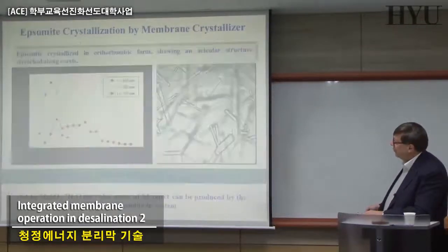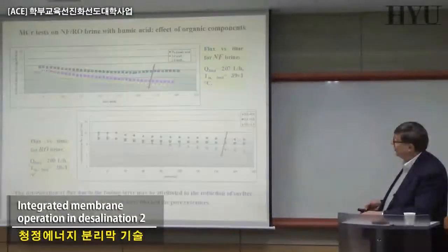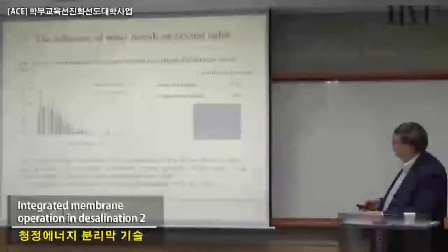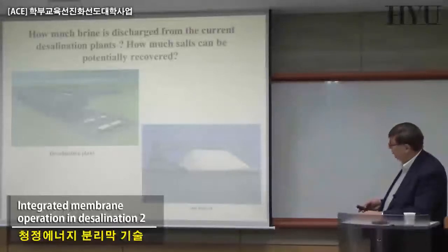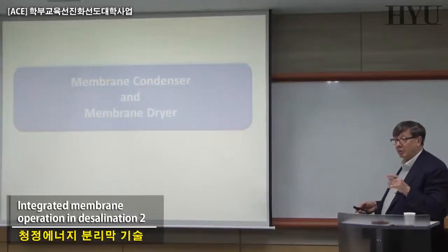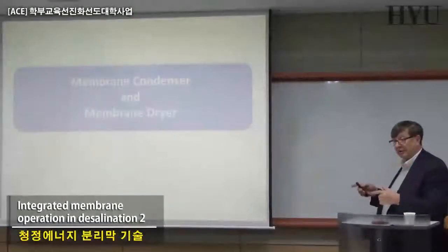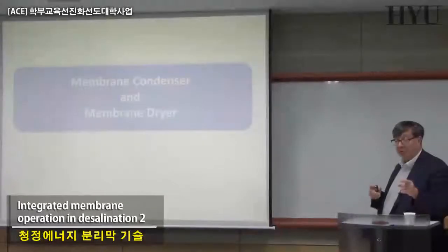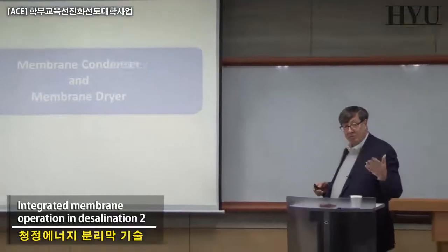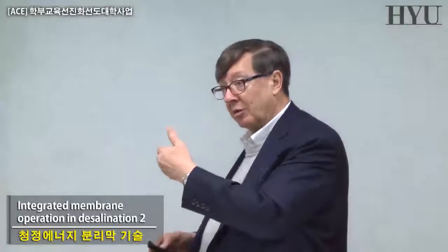Quickly, to show that with this system, you can produce epsomite, as I was mentioning before, or you can produce thenardite, which is another one of these, but we will discuss that in another moment. I want to show now that this system can be utilized not only for what we've been discussing until now. We have been discussing distillation and crystallization. In both cases, what you have been doing is to warm up one side of your membranes. Membranes all the same, but you're warming up, inducing evaporation and going across, etc.